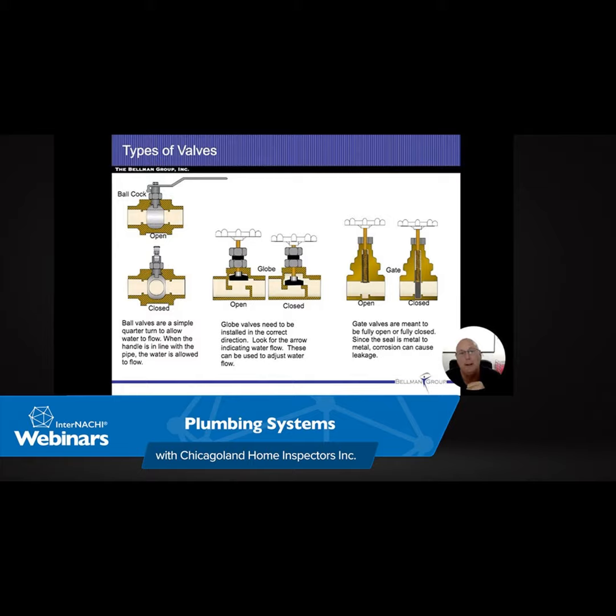Once it gets past the top of the water heater, then we want to induce fresh air with it. We want to bring that temperature down. Typically, you're going to be exhausting somewhere around 300 degrees of heat from the top of a water heater, and I'm talking about before the draft hood. Afterwards, it'll drop down to under 200 or 200 degrees once I get 70-degree room air mixed in with it. I think that summarizes our water heater.